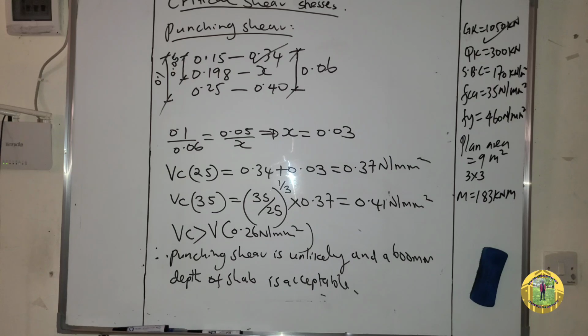And what if the punching occurs? So these are the remedies, or the precautions, you can use if the punching shear can occur when designing a pad base for a footing of a column. Punching failure occurs when the concentrated load from a column causes the concrete slab or footing to punch through, failing in a cone shape around the slab.